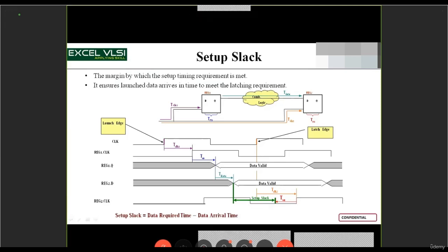How to calculate intrinsic delay? Intrinsic delay is calculated by the tool. As a user, you can't do that process. It's an interpolation process done by many simulations. So the intrinsic delay is again calculated by the tool itself. The tool is automated in such a way that when you're not giving any transition and load values, the delay that particular cell is representing is called an intrinsic delay.